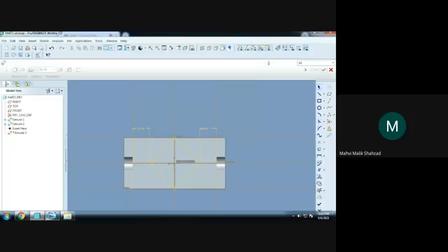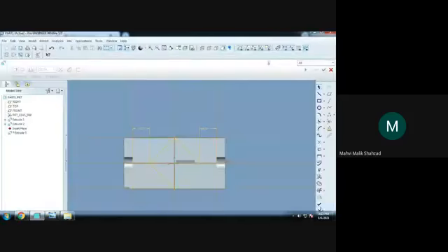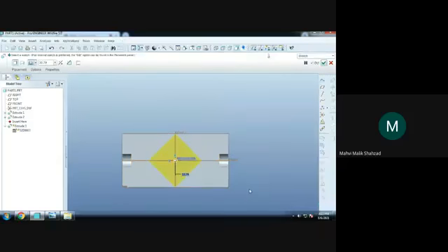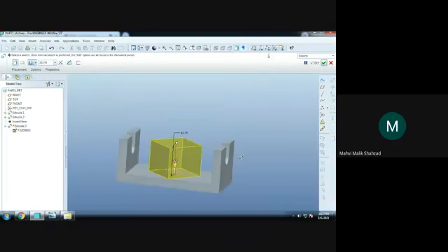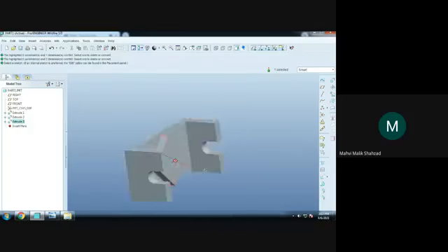Now, is it clear? Yes, sir. Again, the height of that square or rectangle is 10 mm. Just see in the front view. So I will click done here. Just see the direction of extrusion. I will give the height as 10 mm. So this portion is clear now.